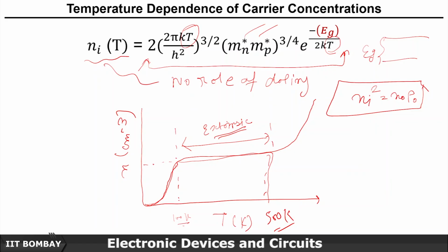Afterwards, the temperature is so high that this is sort of a breakdown region, and a huge number of electrons will cross the barrier. So that's why the relation goes something like this. Initially it goes gradually, it takes thermal energy, and then it saturates for a good range of temperature. If the temperature goes more than that, it gets so much energy that the N will increase dramatically.